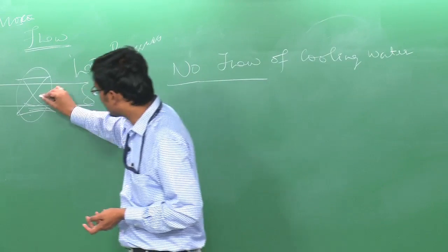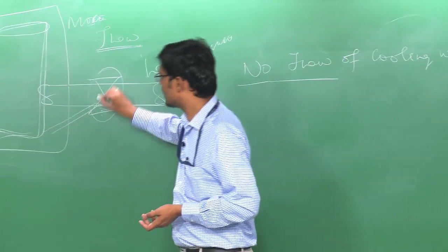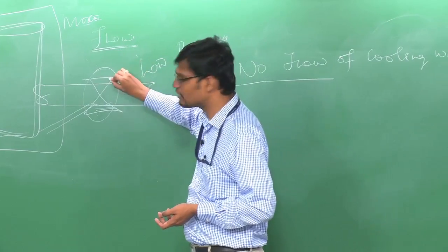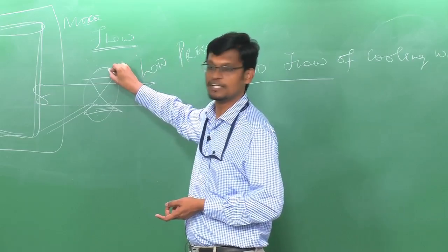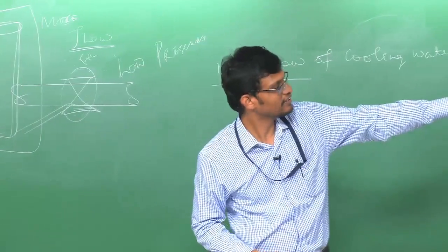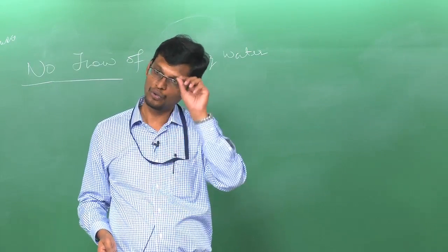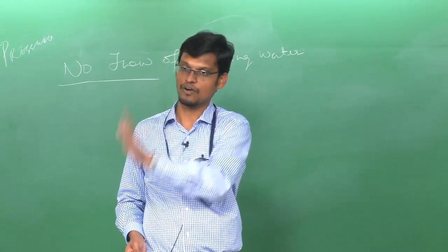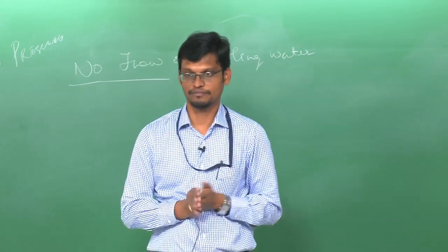Or if this valve is in an area where there is a possibility of jet fire and the valve can get damaged, but from an emergency perspective you want to close it from the control room even in the event of a fire, then what is the fire rating of the valve? So all those things will come up once you start discussing: take the P&ID, mark the node, go to each of the parameters, use the guide words, arrive at the deviation, cause, consequence, and control measure.